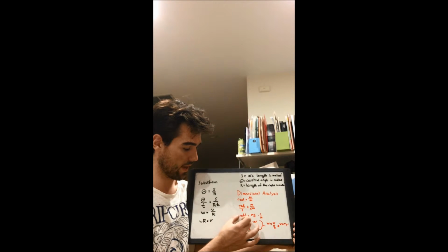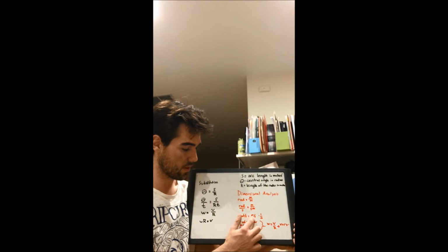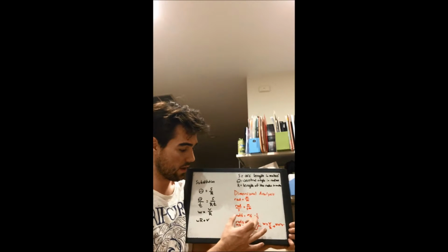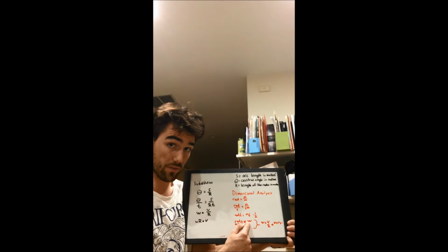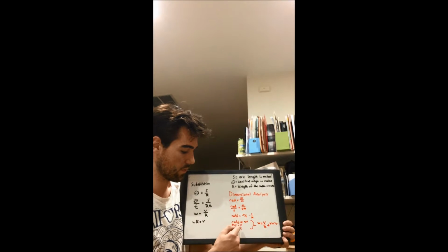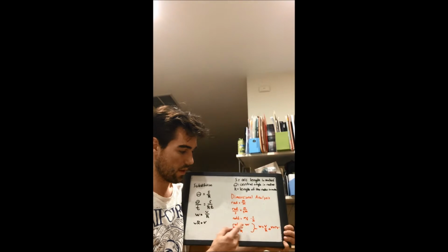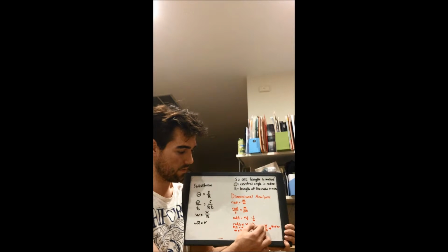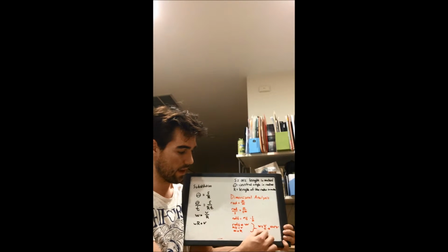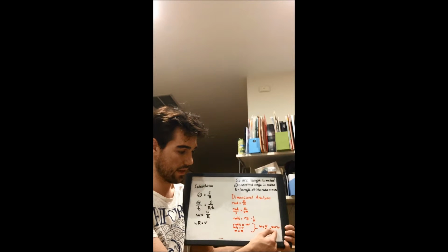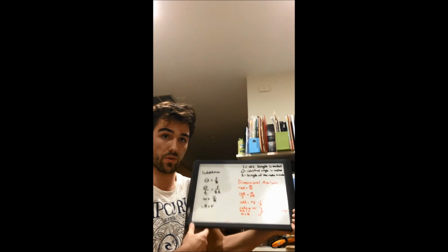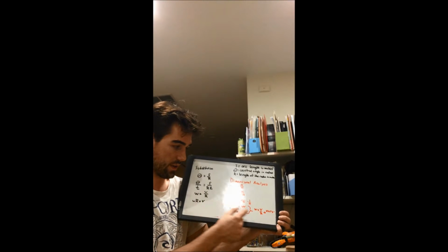So we end up with radians per second is equal to meters per second times 1 over meter. I split these up to highlight that radians per second is actually equal to the angular velocity, as well as the meters per second is equal to the linear velocity. And then the simple movement of, I put these back into their original form, w equals v over r, and then simply multiplied the r to both sides and ended up with v equals rw, which is the exact same derivation as we reached over here.